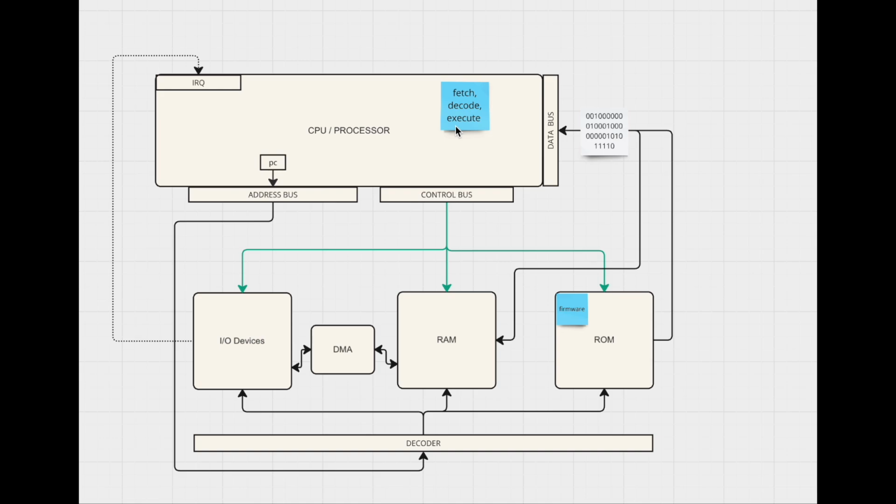And so the next instruction happens, and usually the program counter just increments by 1 to go to the next instruction, and then does the next thing and the next thing and the next thing following the fetch, decode, execute cycle. So it's also possible to jump between instructions.